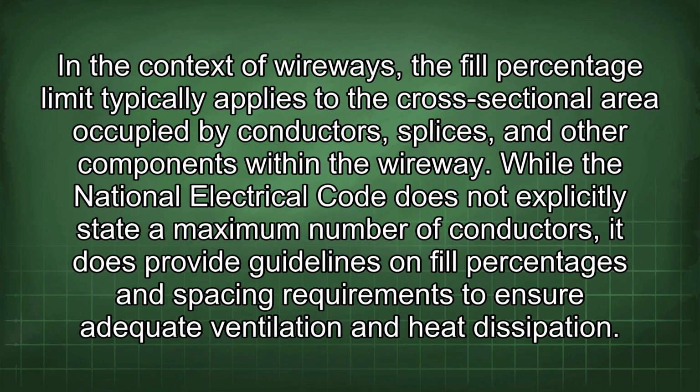In the context of wireways, the fill percentage limit typically applies to the cross-sectional area occupied by conductors, splices, and other components within the wireway. While the National Electrical Code does not explicitly state a maximum number of conductors, it does provide guidelines on fill percentages and spacing requirements to ensure adequate ventilation and heat dissipation.